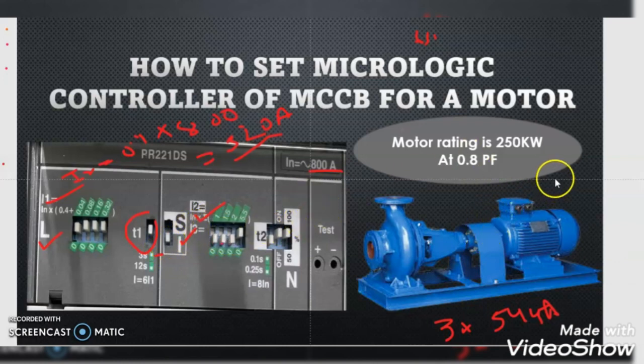Suppose the fault current of this motor is 6K. The prospective fault current at the motor level is 6K, but you set this short circuit fault current at 5 kilo ampere. Then when the short circuit happens, the maximum possible short circuit current is 6 kilo ampere, but you set the short circuit current rating for this circuit breaker to 5 kilo ampere, though it is capable of taking 8000 ampere of short circuit current.